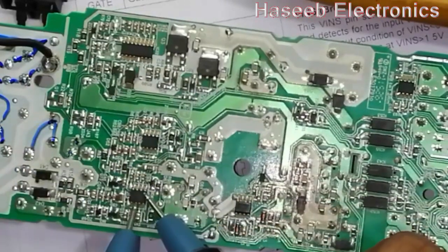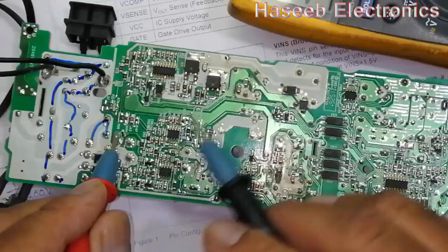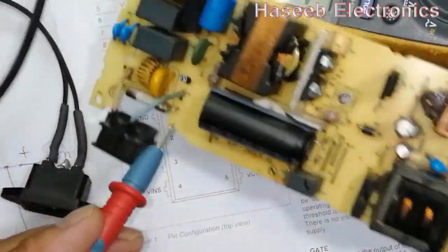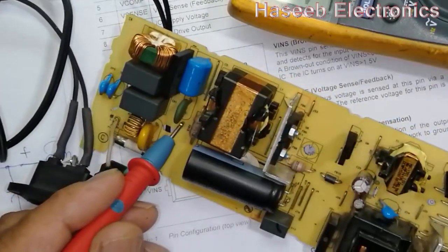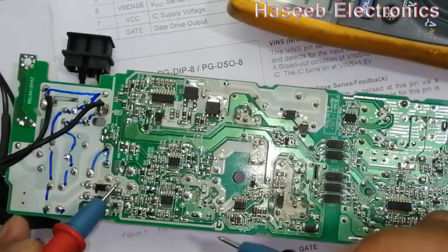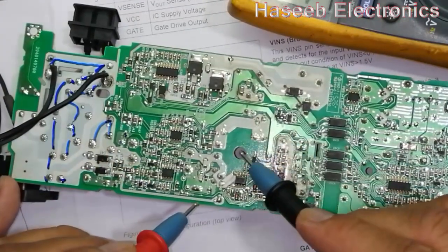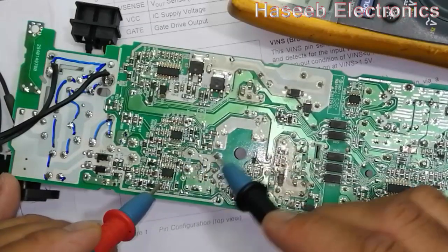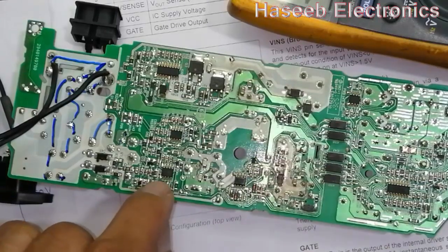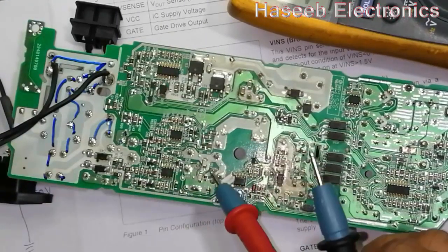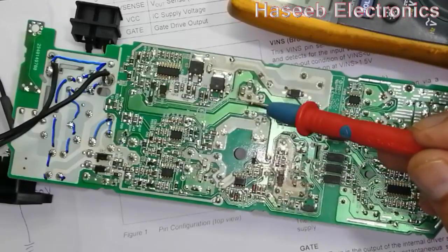I sense, V sense. I sense how much current is flowing from this current limit resistor, current sensor resistor. The amount of current is applied through this resistor, and the amount of voltage will be sensed by the 1, 2, 3 resistors. So it will sense the amount of voltage. So this IC will maintain its duty cycle to maintain the voltage level of 410 volts at this capacitor.